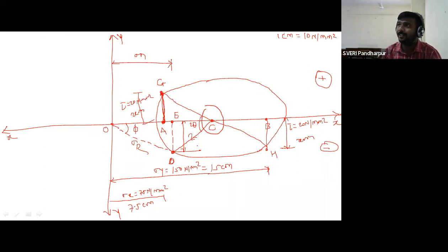So now, why will this Mohr circle not be applicable for case number 1? By solving the problems on case number 2 and 3, why is it not applicable for case number 1? In case number 2 we have sigma y. Sigma y is not given in case number 1. What is our case number 1? A member or body subjected to uniaxial stress.